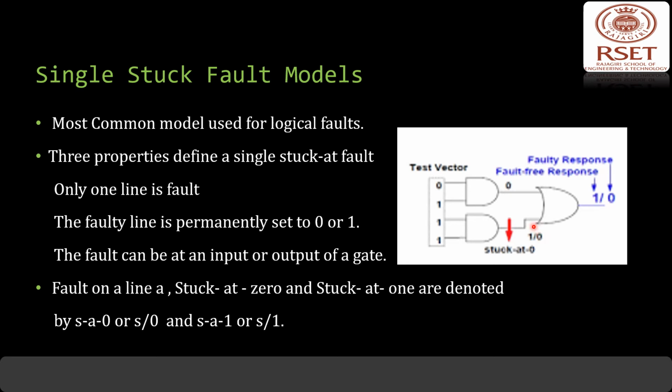Alright, now this error is propagated here. If it was a fault-free response, it would have outputted a 1. But since here we have a stuck-at-0 fault, the response is a faulty response and therefore the response is 0. Hope you understood what a single stuck fault is.